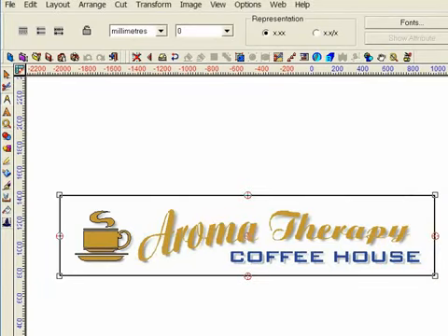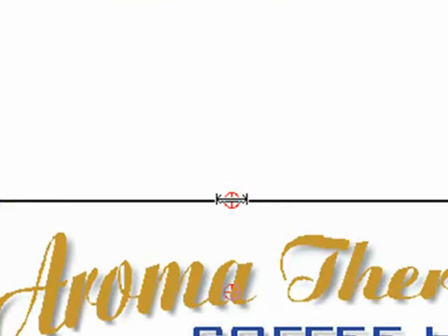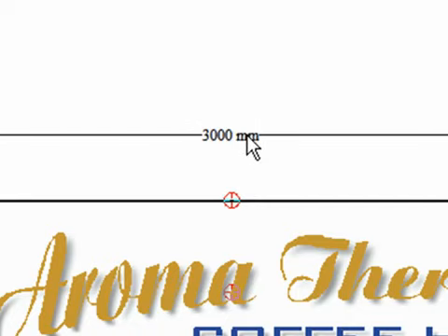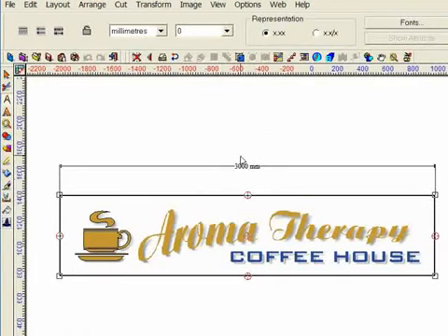Okay, with my properties set up, it's now simply a case of adding the dimensions. To do this, I'm going to move my cursor over the middle nub of my object. When I do this, you will notice a double-headed arrow symbol appears on screen at the point my cursor is placed. Hovering the mouse in this position, I simply left-click and drag the symbol away from my object. Now when I release the mouse button, my object dimensions are displayed above. I will now need only repeat these steps to display the object height.